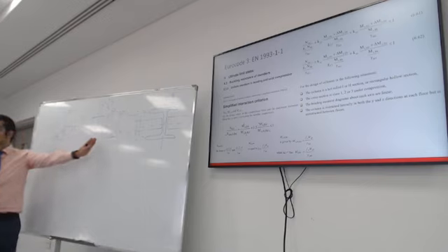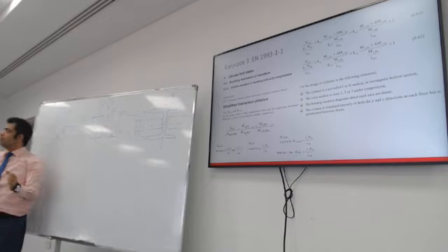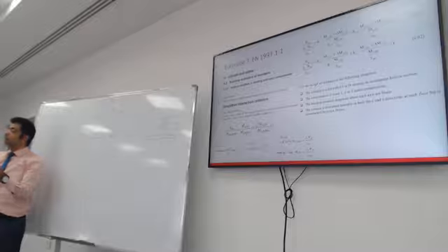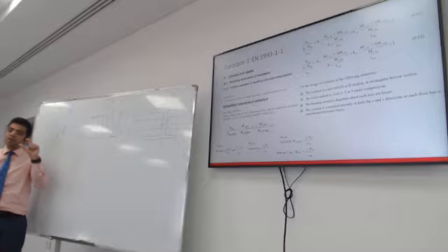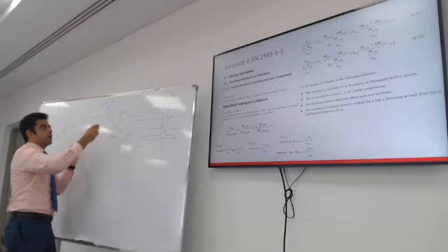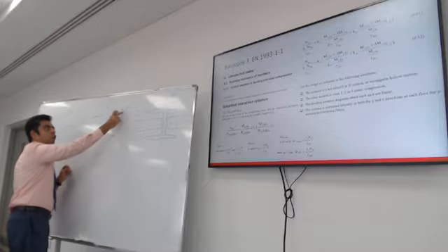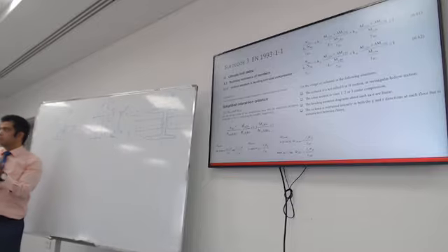Does that make sense? We talked about the moment stress distribution due to moment on a cross section before. The tail of the arrow will cause tension, the tip of the arrow will cause compression, and this compression, this stress here, will add to the axial compression.